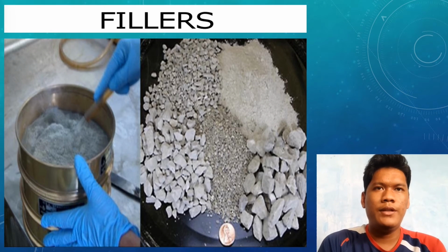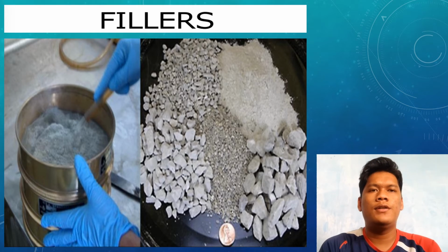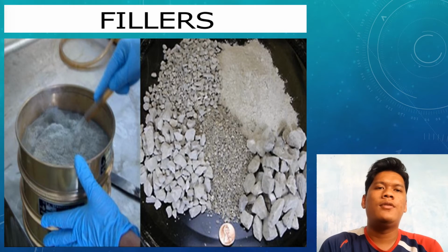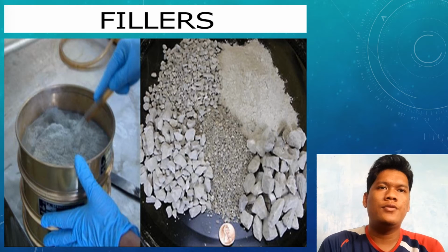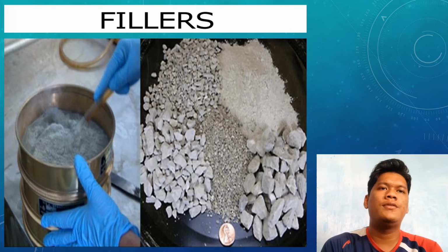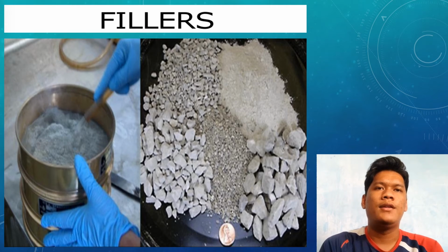And mineral filler makes up less than 6% of the hot mix asphalt concrete by mass and generally less than about 3%. The particles larger than the thickness of the asphalt film behave as mineral aggregate and contribute to the contact point between individual aggregate particles. The gradation, shape, and texture of the mineral filler significantly influence the performance of hot mix asphalt.